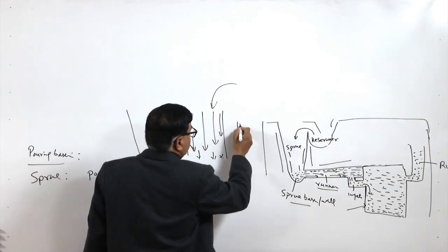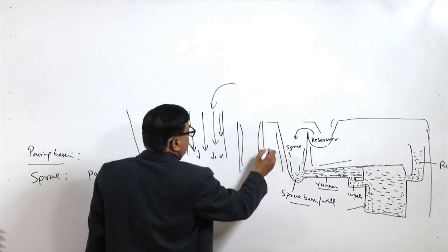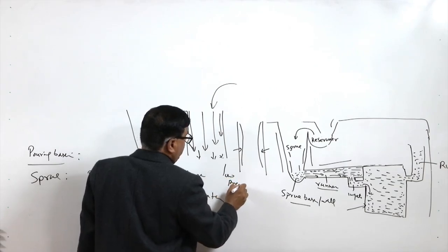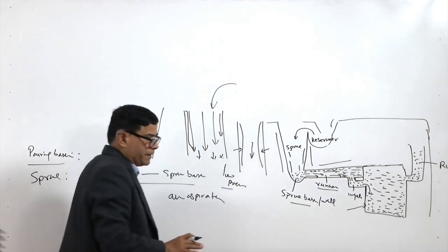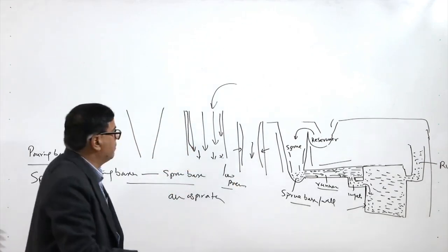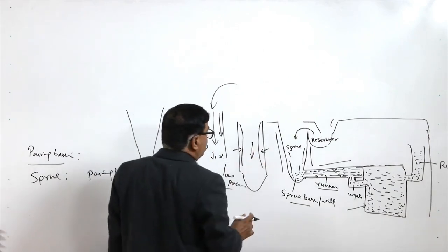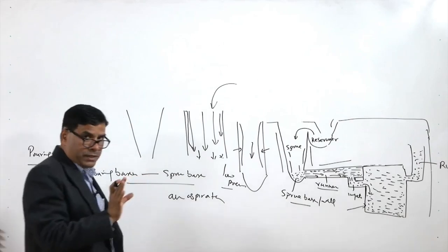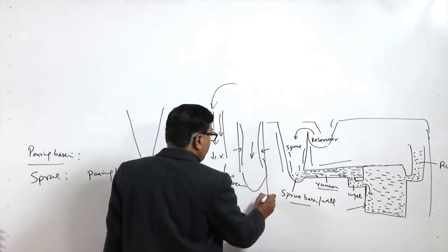This separation in the lower zones leads to the development of low pressure regions, due to the increasing velocity of the molten metal during its journey from the top to the bottom of the sprue, and that leads to air aspiration from the porous molding sand.